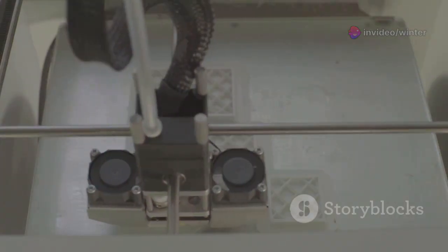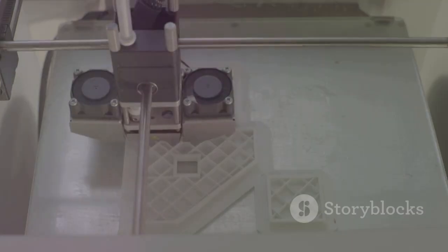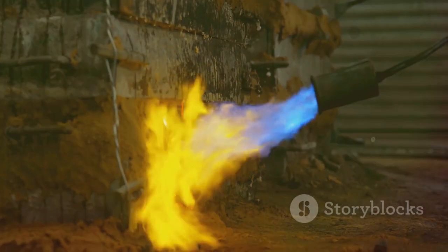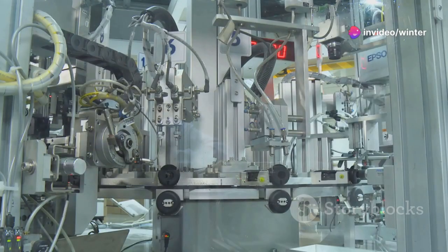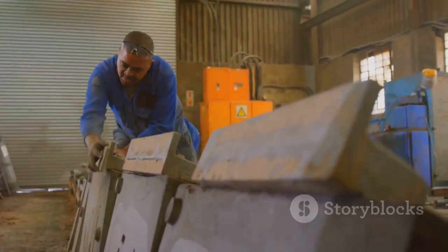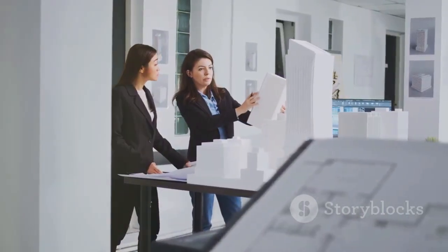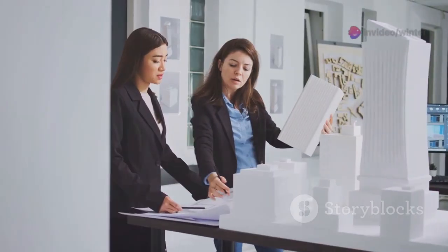Hot runners keep plastic molten all the way to the gate. No runner scrap, faster cycles. Hot runner molds cost much more upfront with heaters and controllers. But for millions of parts, the material and time savings pay off. The choice is a classic trade-off: low upfront cost and more waste, or higher investment and lower cost per part.